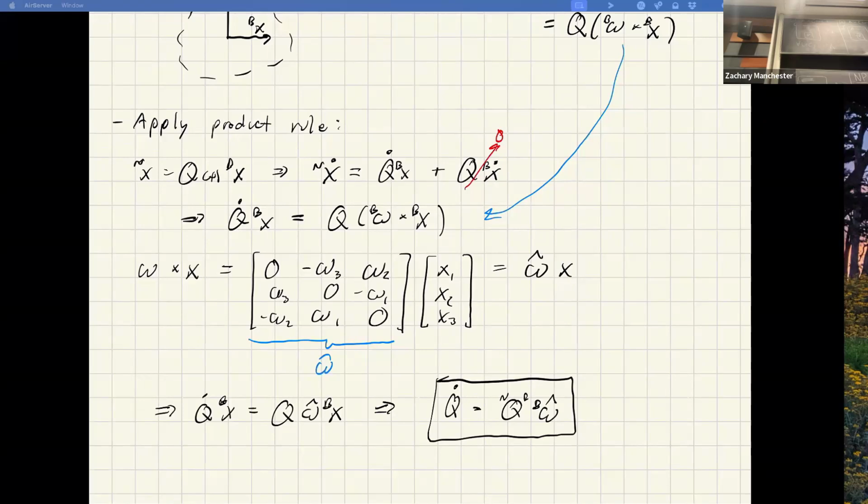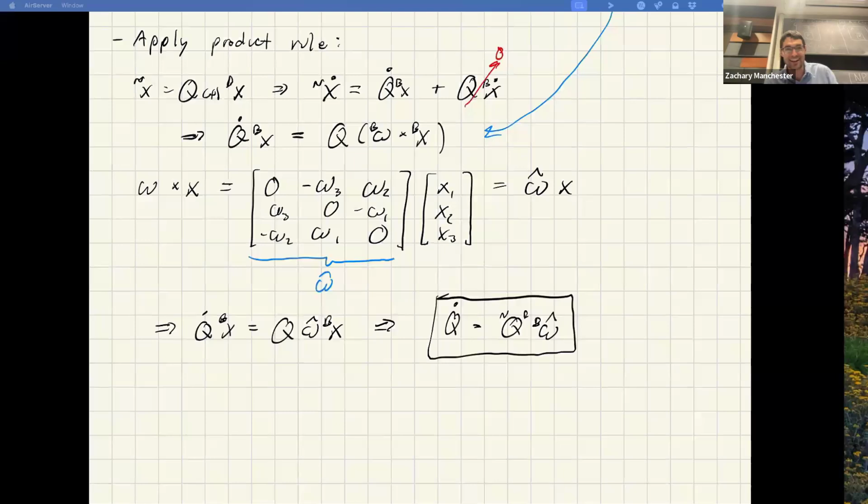Basically flip sides. It's because the rotation matrix going the other way is just the transpose, right? So if you transpose the whole equation, you'll end up with omega hat in the n frame on the left side in that q times omega hat thing. It becomes omega hat times q the other way. Make sense? Yeah. So it just flips out. But yeah, you literally just plug the rotation in, flip it around. It's easy. So as an exercise, you can figure that out.